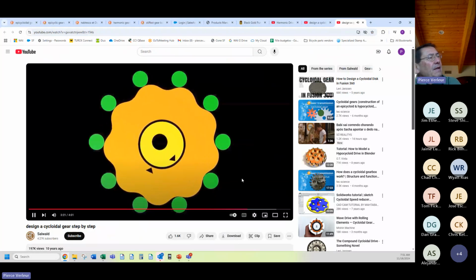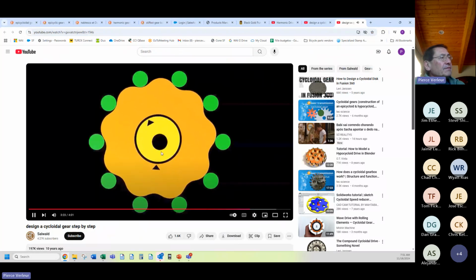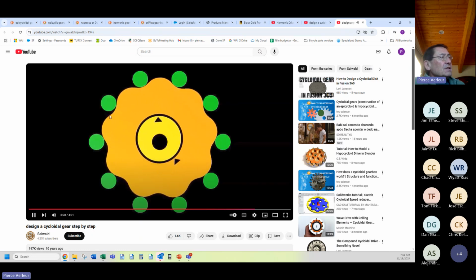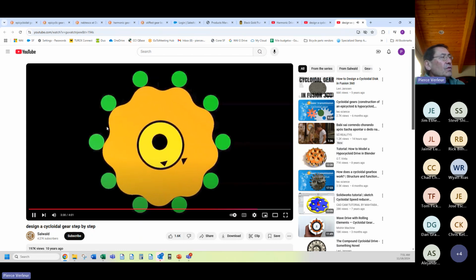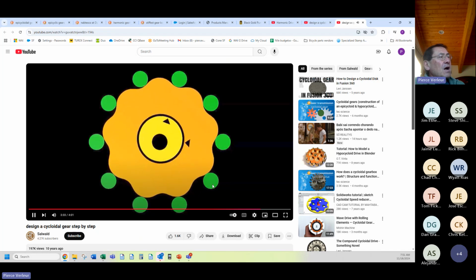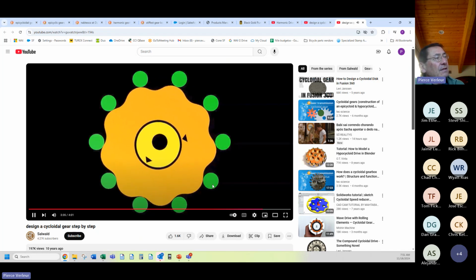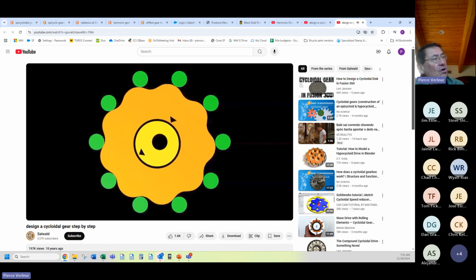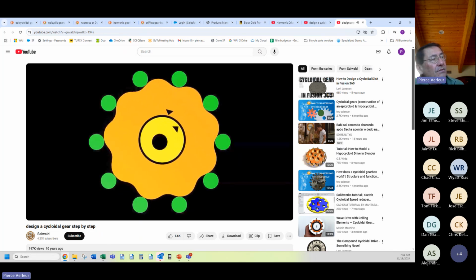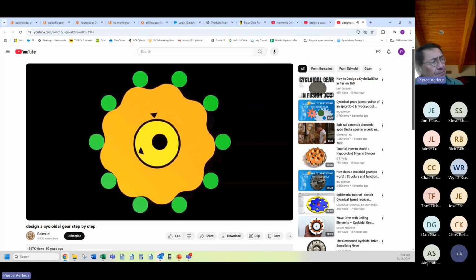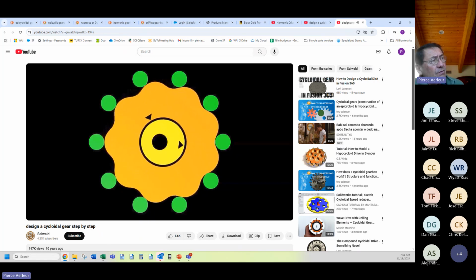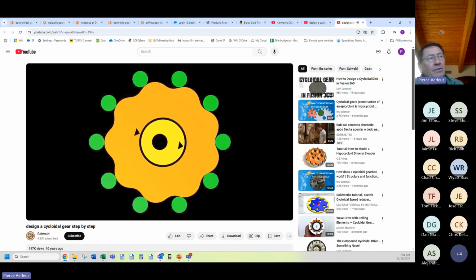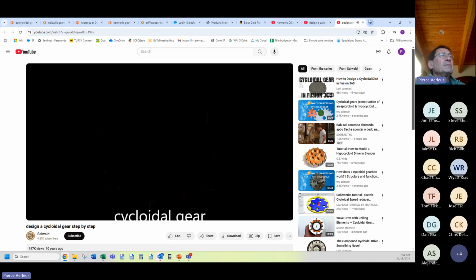This is an epicycloidal. The input shaft turns an ellipse that causes the lobes to move along these stiff rods, and you get a reduction ratio in the opposite direction. Note the orange section is moving opposite to the yellow section, which is your input shaft, and it's moving slower. There's a fascinating principle here. We don't have a lot of time, so we can't listen to Beethoven anymore.